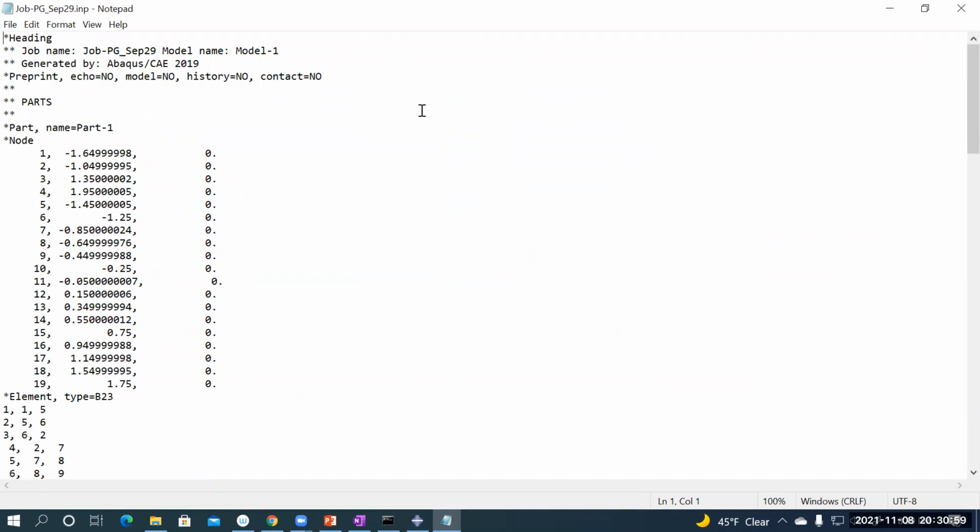That's how the bigger domain is broken down into smaller domains, right? If you have used rectangular elements or triangular elements, the K matrix is getting assembled, the smaller domains are getting assembled to the bigger domain only through these nodes, and the nodes' x and y coordinates, if it's a 2D problem. For a 3D problem, x, y, z, three directions are there.